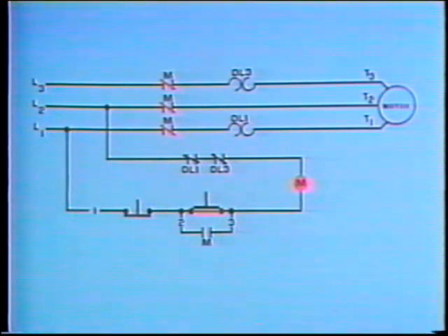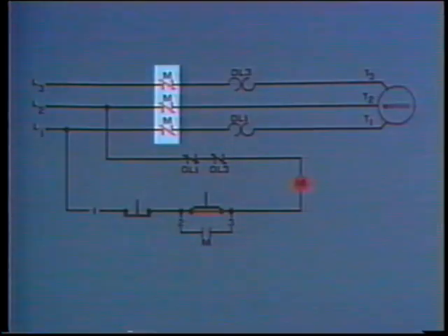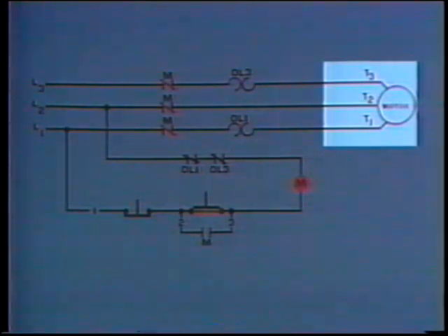Because the motor starts and operates as long as the start button is held in, the electrician can eliminate the entire motor circuit. He knows that the main contacts are closing and that the motor is working correctly. If any of these components were malfunctioning, the motor would either not start at all or not continue to operate, even with the start button held in. The electrician can now assume that the problem is somewhere in the control circuit.